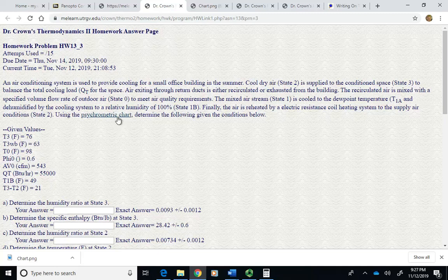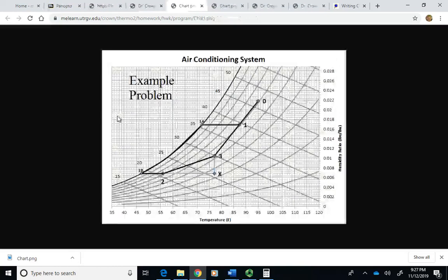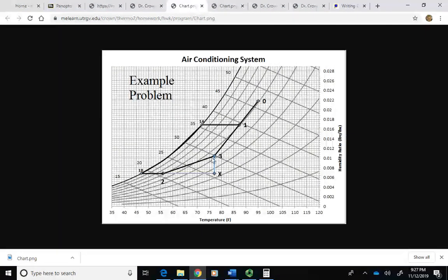This makes a whole lot more sense on the psychrometric chart. So let me show this. So here's my space, and these are the conditions I want for my space. So it's 77 degrees and looks like about 50%. This is 10, 20, 30, 40, 52%, maybe something like that, relative humidity. It's got a humidity ratio of a little greater than 0.01, so maybe 0.012.